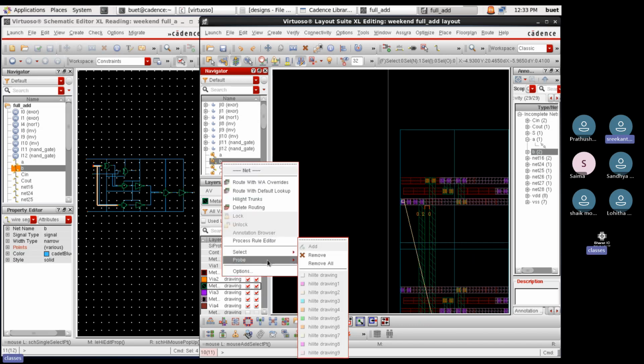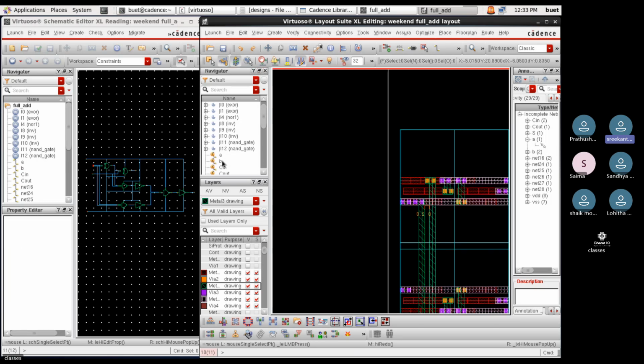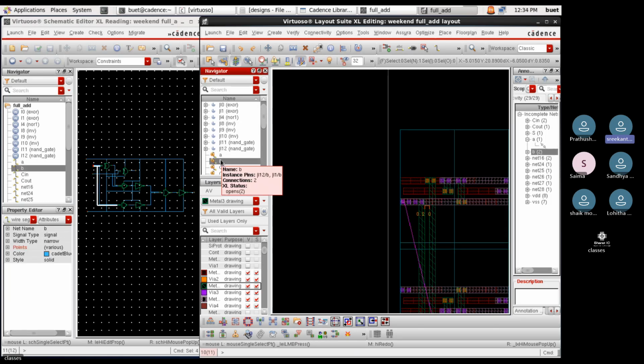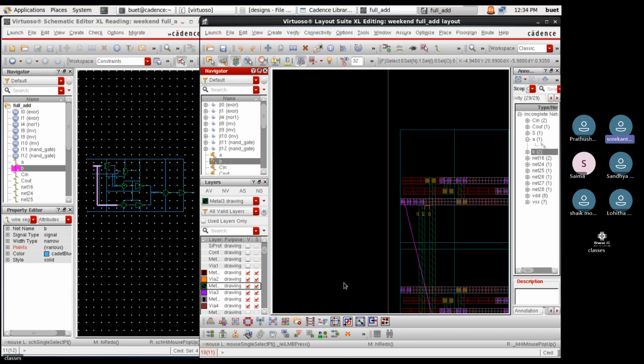For the same via, whatever previous via is there, right? For that via only you provided 4 rows, right? Yes, because what happened is, if we put one via of the same family and there is a spacing issue, it will flag a DRC. So what I did, I overlapped each other very perfectly, and even it is connecting this M3 metal also. Okay. Is it now clear what I have done? Yeah.